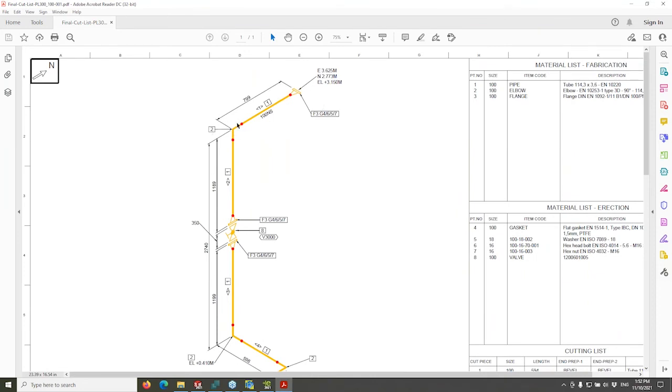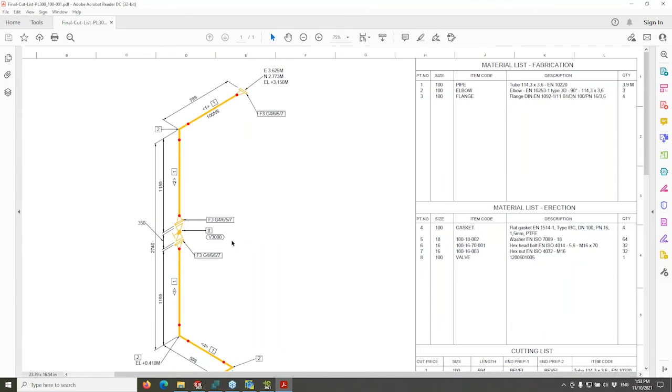You can change the styles. Maybe you want to dimension to the welds. Maybe you also want a dimension to weld gaps. Maybe you only want to do center lines. You have full control over how you want these to look. Converting the 3D models into the relevant symbols.